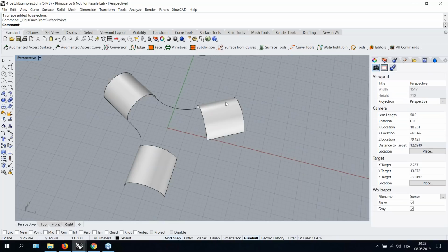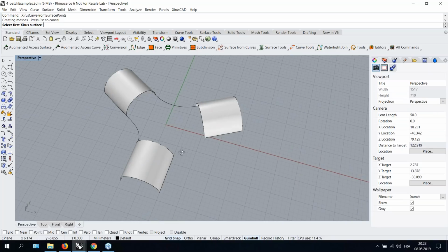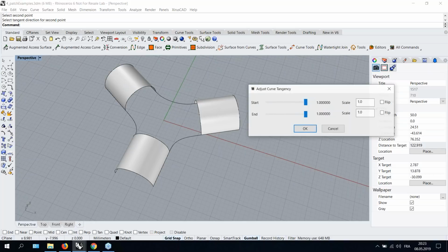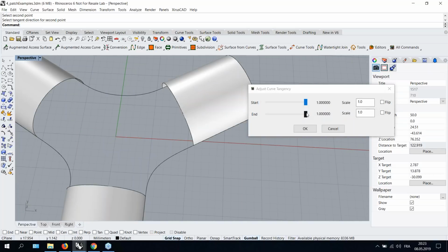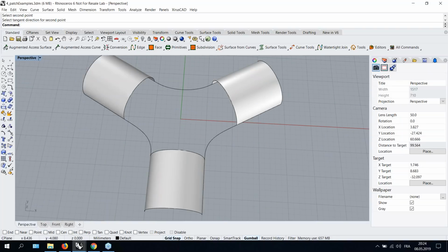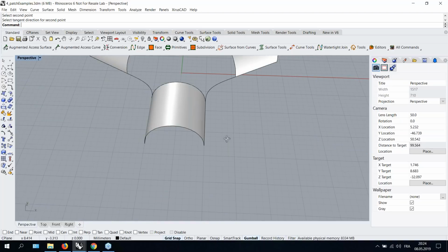We have this curve tool, which allows us to create curves which are smoothly connected to their surrounding edges, as you can see here. And then when you execute the command, you can actually choose the bending between the curves through this dialog window, and it's always smoothly connected to the two endpoints. And so this is how we created all these 3 curves in between these half cylinders.